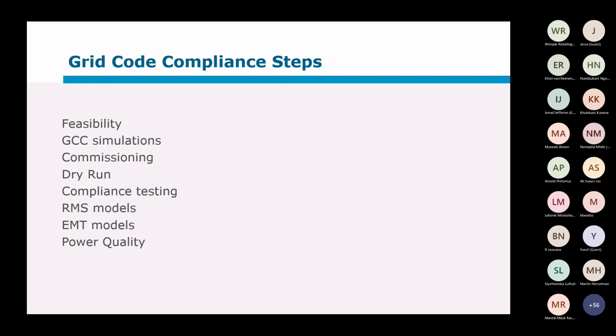Okay, the power quality question. It's up to the 50th harmonic as per the grid code. I would probably like to see it up to the 60th harmonic. Most power quality instruments can measure that, but there is research work being done on different levels above the 50th harmonic, up to 9 kilohertz, to get appropriate emission limits and compatibility levels there. But at the moment, just the 50th.